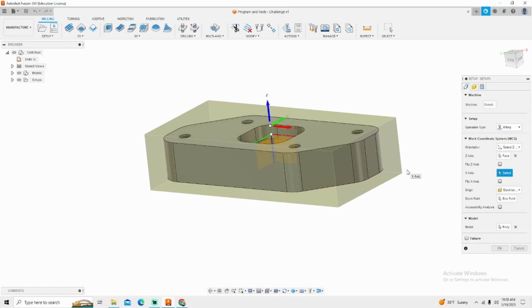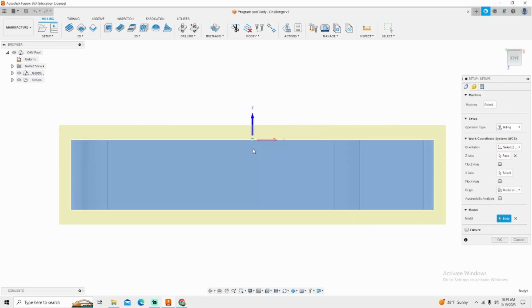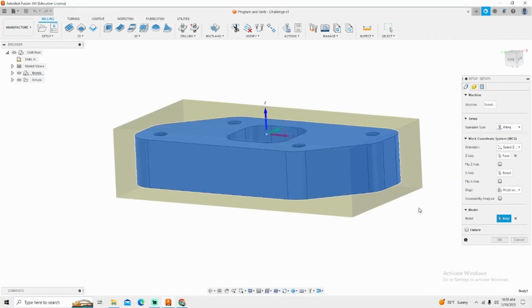Now if this was a finished part, let's say this is like an OP3 or OP4 where it came off another machine or it came back from external processing of your facility. Let's say you need to engrave some part numbers on a ground surface, but you don't want it to be engraved before the grinding process. You want to engrave it afterwards to ensure you're hitting your engraved depth. This is something that I have done quite a lot out in industry. You would want to go to model origin. See how it actually highlights my model? Now my origin is directly on top of my part. This makes it very easy again for finished parts to be able to pick up on a known origin.